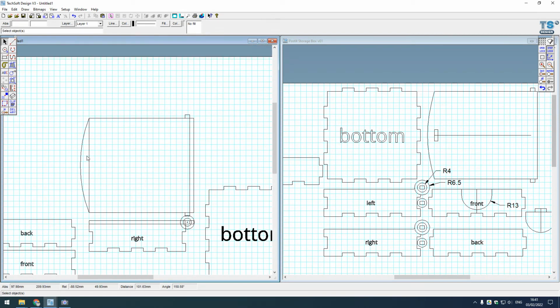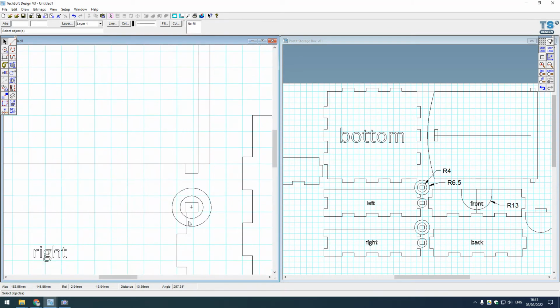Okay, so it's almost like this line here and this line here are basically just construction lines. So I think that's what I want to do. No, I'm going to leave it as it is. There we go. I think I'm going to be okay with that. Let's now just select the image here. And I'm just going to pull this away with the grid lock on another 5 millimeters so I can see that everything's mapping out nicely. So can I select this and delete it? Yes, I can. And now you can see that hinge unit is looking really nice.